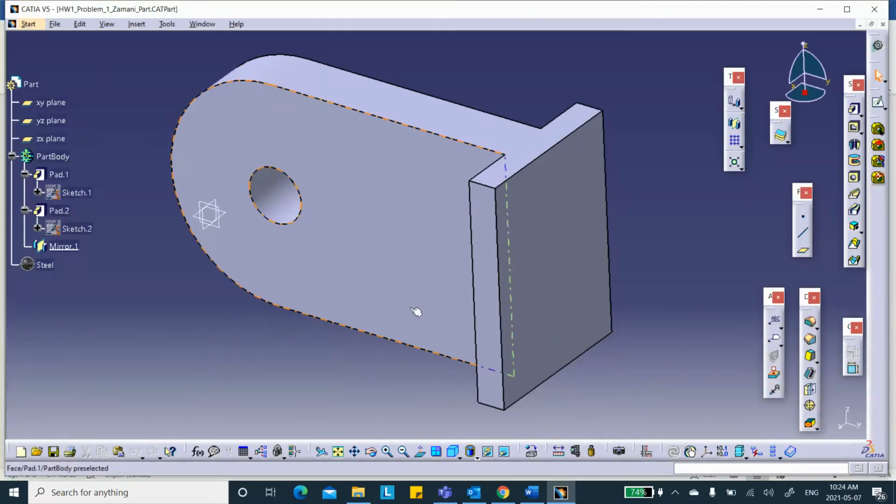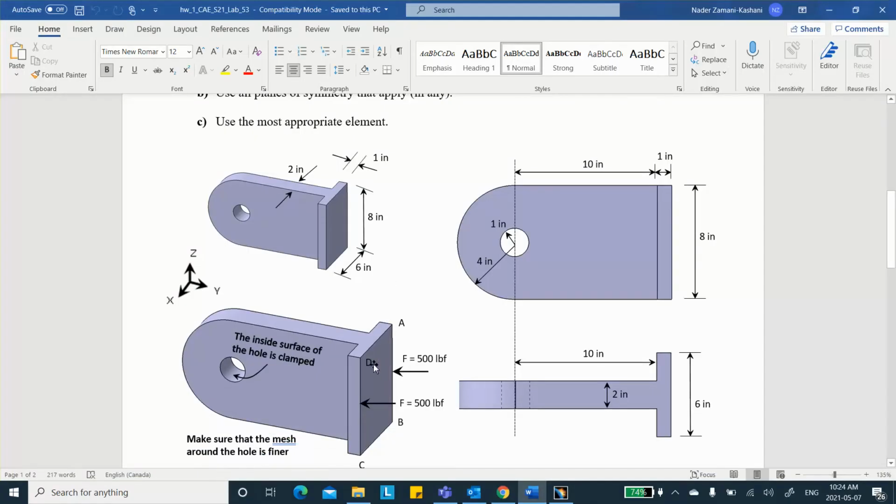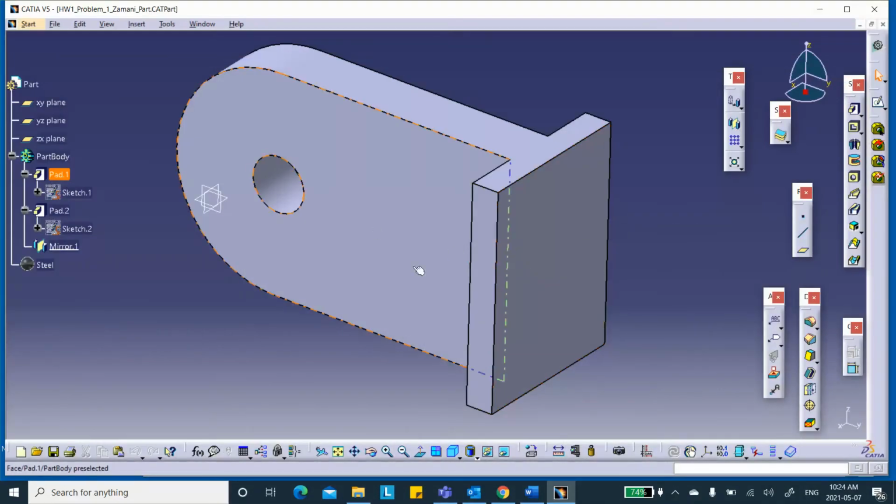So, yeah, right. Now remember, this particular problem has 2 planes of symmetry. You have to cut it with something parallel to the YZ, and in my case, because I did a mirror, I can use the YZ plane, and then cut it with something that's parallel to XY. Now, I already can cut it here. See that? I already cut it with YZ, you get half of this. So let's go get the cut.